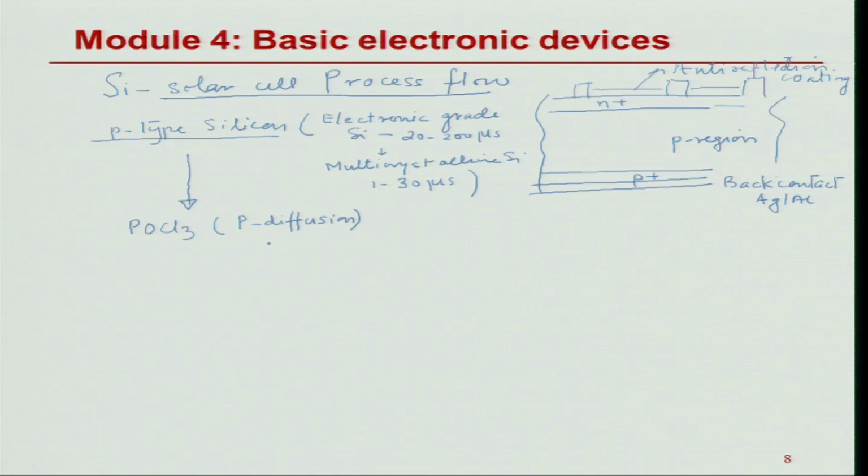As it comes to the surface of the silicon, what happens is POCl3 oxidizes, one brings in the oxygen along with it, and it changes into P2O5, which reacts with the silicon and gives phosphorus plus SiO2. And this phosphorus is then doping the original p-type silicon to whatever the process is desired.